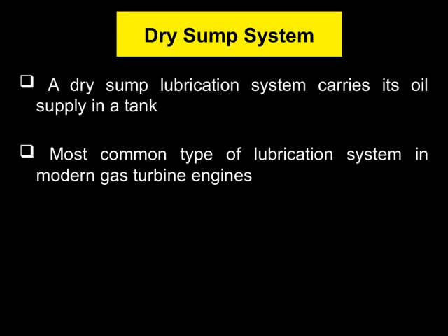It's actually the most common type of lubrication system used in modern gas turbine engines. The main advantage here is that by having the oil in a separate tank, we can better control the oil flow and ensure proper lubrication even under varying operating conditions. This setup helps maintain a steady supply of clean oil, which is crucial for the engine's performance and longevity.